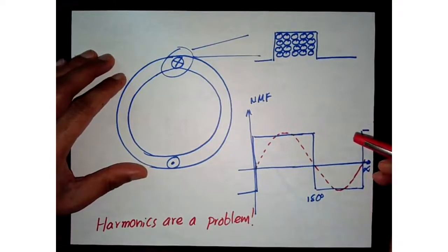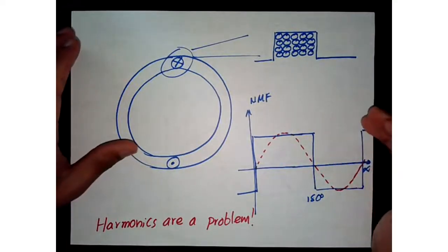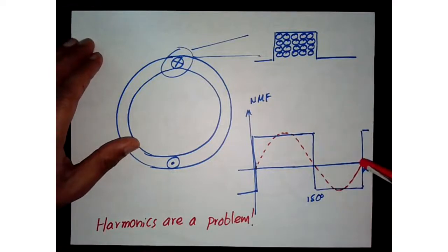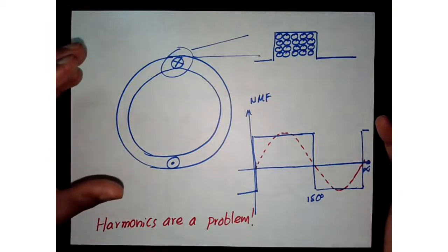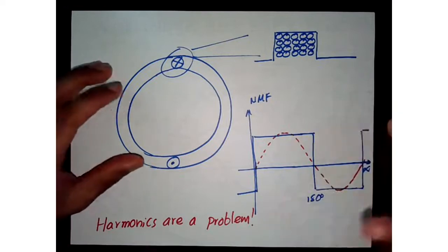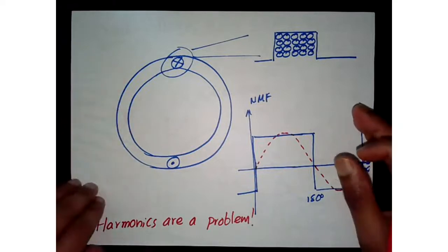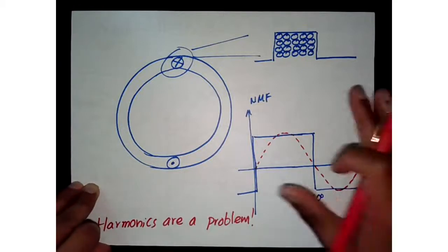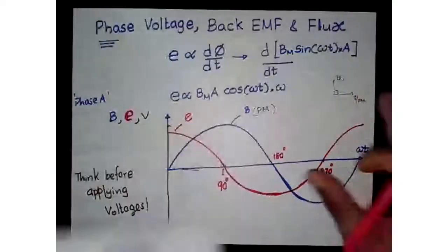So of course, from the Fourier analysis, we know that this is going to have more harmonics than our previous case. But this is still useful to a certain extent if you don't care about torque ripple, if you're not worried about truly non-sinusoidal back EMF. These machines are also applicable. These can be used. It reduces cost of manufacturing production significantly. Okay, so these are another type of machines that you come across.